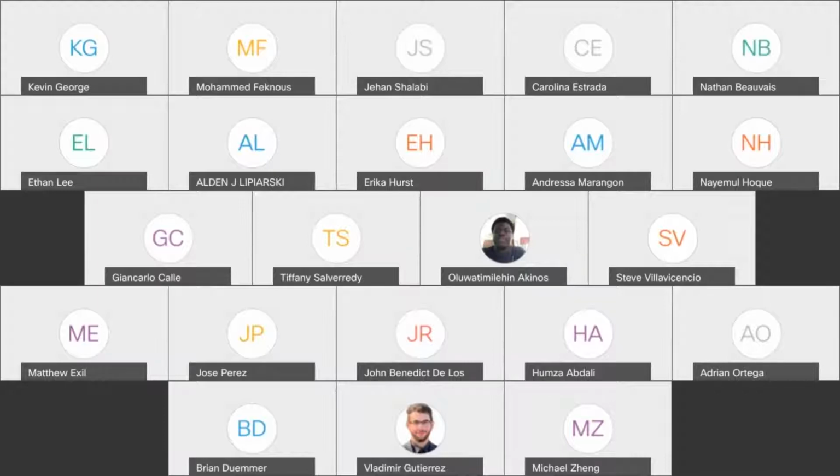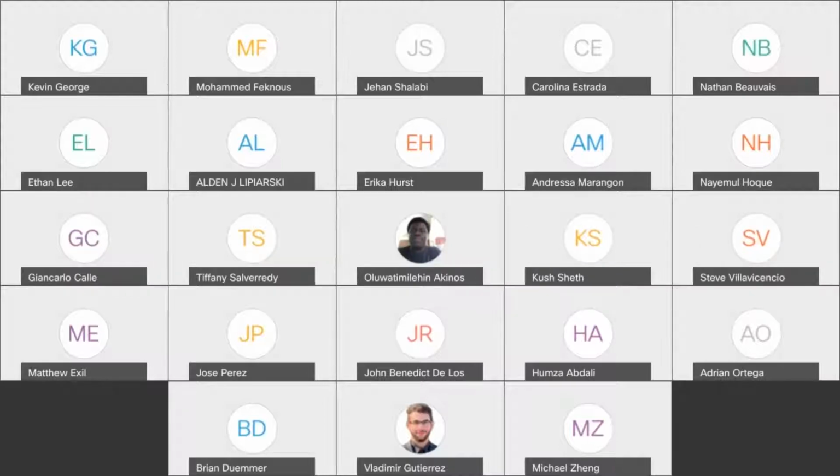So in Python, to use libraries, we typically import them. I'm going to use the function import, and the library we're going to use is called RPi.GPIO. This is our GPIO library on the Raspberry Pi platform, and we're going to call this into a variable as GPIO. Oh, we can't see your screen. Oh, my apologies. So now you can see it.